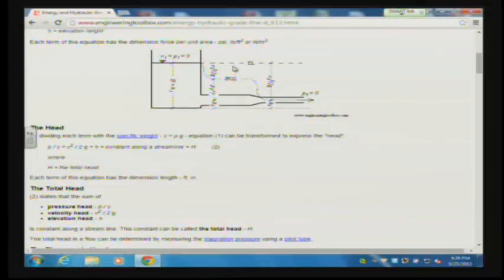It's like here, it's in a tank. Here in this diameter pipe, we have a relatively fixed v squared over 2g term because the velocity is going to be approximately the same as long as it's incompressible in this pipe, if it's the same diameter. So my hydraulic grade line is going to be some distance below the energy line.